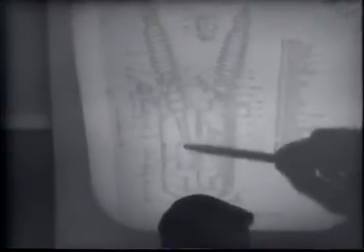Oil is used as the major insulation inside the tank. It allows much closer spacing of all the components. As you can readily imagine, this tank is probably some 3 feet in diameter, but yet we have energized surfaces, as I recall, basically 8 to 12 inches from a grounded surface there. There again, due to the high dielectric strength of oil.